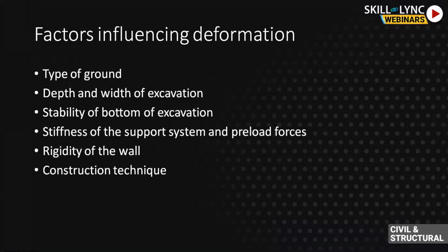When it comes to the type of ground, certain grounds are very stable and have a very good SPT value, so the ground itself is stable. When there is very loose ground, for low SPT N values, there is a possibility of deformation. And the ground may also be very rigid, like with boulders. In certain conditions, walls cannot be driven, for example sheet piles.